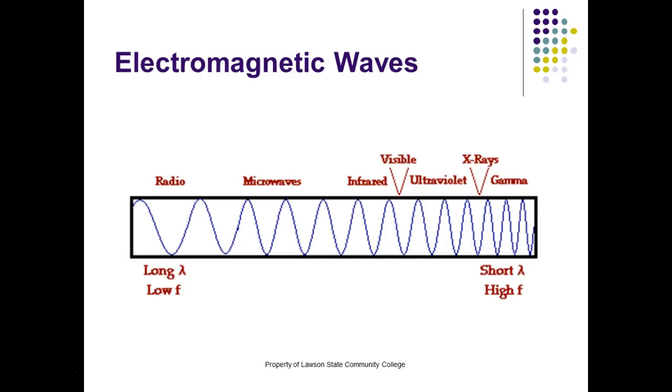So with light, we don't have to worry about electromagnetic interference either, right? This is why fiber optics is pretty popular. This is one advantage fiber optics has over copper wire: it's immune to EMI. EMI can induce a voltage, but it can't change light. That's one big advantage of fiber over copper, that it's immune to noise. If you're immune to noise, it means you can start pumping the frequency up.